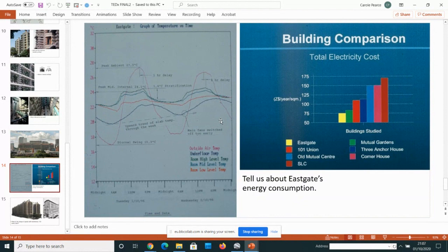The building got hotter and hotter, and I got more and more worried, and I was about to leave the country and disappear altogether because everything looked as though it was failing. And then we found the fans had been off for 3 months. It took another 4 months for the building to cool down after we found the mistake. That was the lag time.